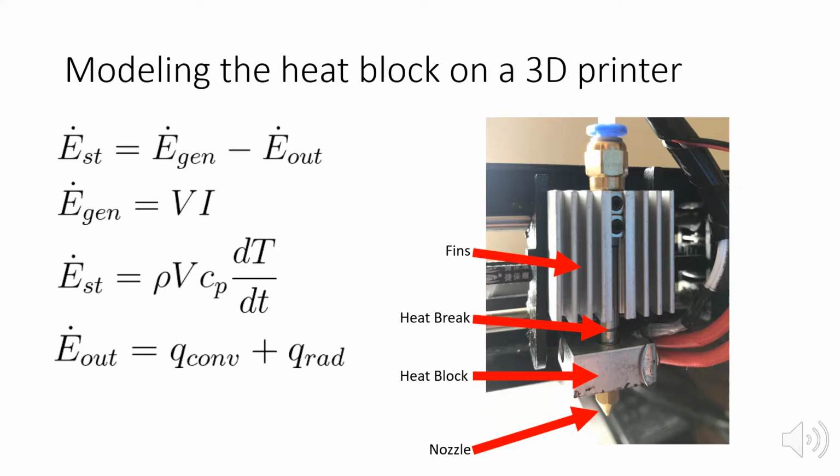This model uses Euler's method coded in Python to solve the temperature difference in the heat block. The model assumes that the heat block is made of T6 6061 aluminum with a constant specific heat. The air properties are set up to be interpolated during each time step as the model heats up. T infinity and T surroundings are assumed to be the same.